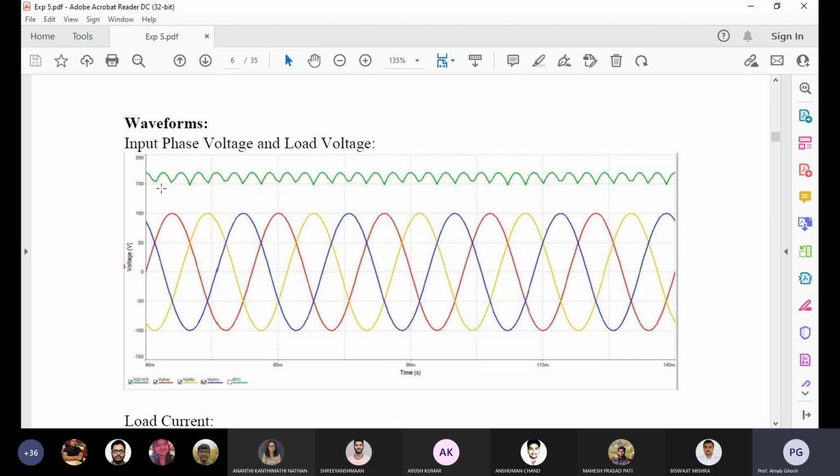You can see the previous case, how much you are getting for 100. You can see over there the average voltage is more than that. If you compare with single phase, the average voltage is more. If you compare the ripple frequency of single-phase pulsating DC with three-phase pulsating DC, you can see it is 3 times more than your single-phase rectified DC.